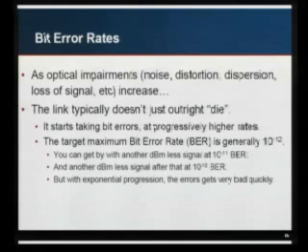When you get to the point where your optic can no longer receive beyond a certain point, you might be able to get 1 dB past that, but you also increase your bit error rate by a power of 10. And as you go down more and more, the bit error rate gets higher and higher, usually by powers of 10, to the point where you have no signal at all.